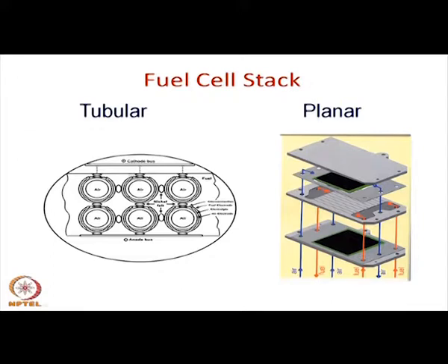In between you have the connections, high temperature contacts basically, but generally it is some kind of nickel felt, which also acts as a vibration absorber. So, it is used as a cushion, and on this side you have a cathode bus and an anode bus. This bus is connected to all the anodes, and this is connected to the cathodes of individual tubes. So, that is how a stack is normally generated.